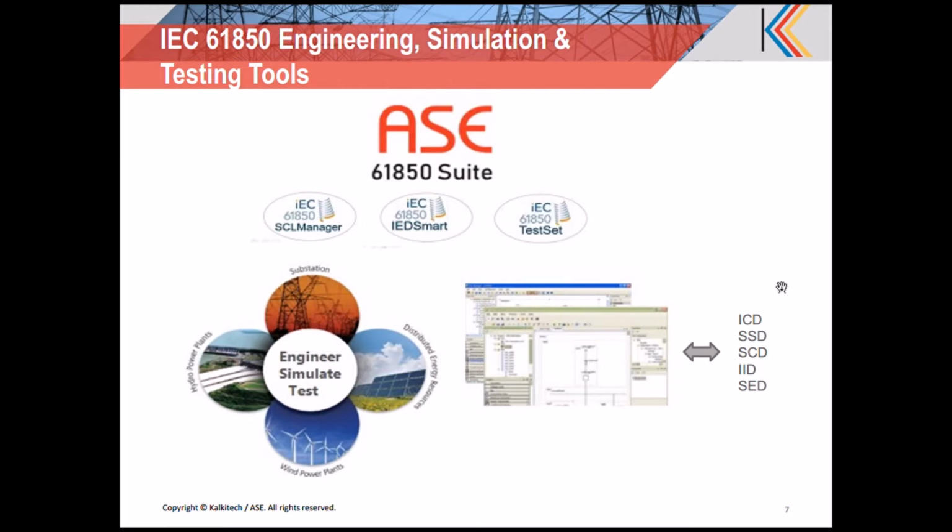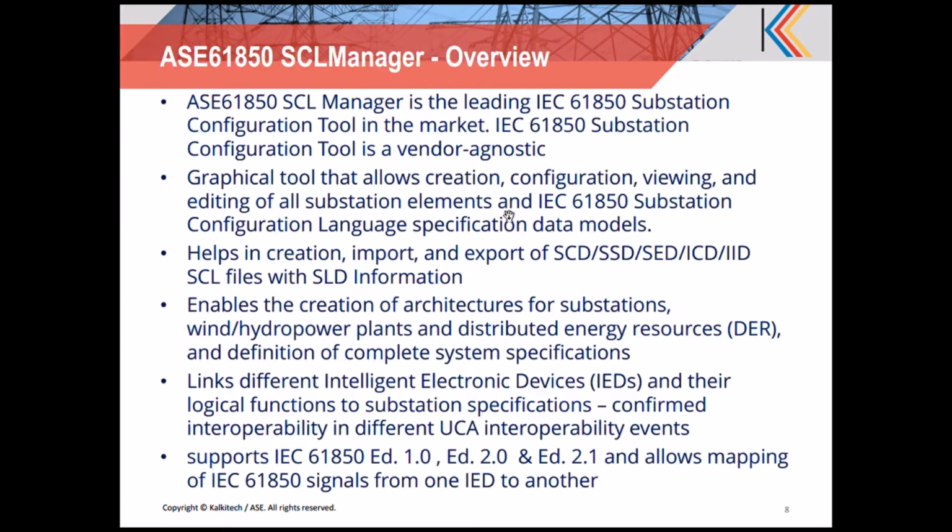This supports all the file types including ICD, SST, SCD, and IID files, depending upon where you want to put this tool. So this is a general overview of the ASE 61850 tool set comprising three different tools. Now moving on to the first tool, engineering, which helps for engineering the 61850. That tool is known as SCL Manager, which is nothing but an engineering tool.